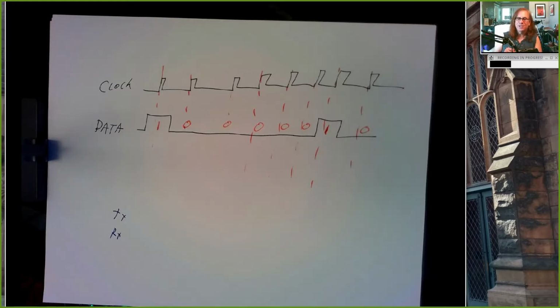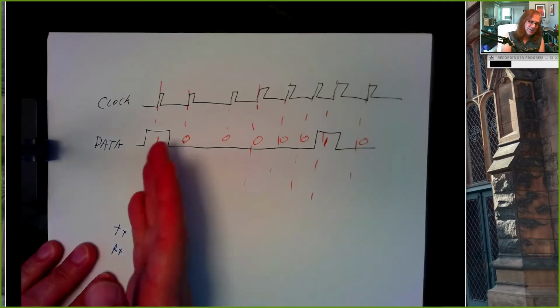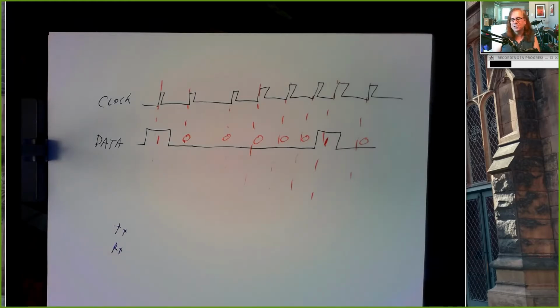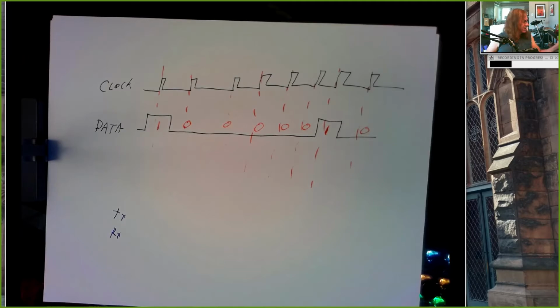I2C, for example, also has a clock line. SPI also has a clock line. But the basic idea is the same. You have some way of sampling a data line, and each time that you sample it, you've got the next bit of whatever information you're sharing. And usually, with RS-232, we're sharing bytes, but sometimes we're just sharing streams of information. We might be sending, you know, over 500 bits that might be broken into chunks of 8 bits for characters, or they might be something totally different. It's really kind of up to you.